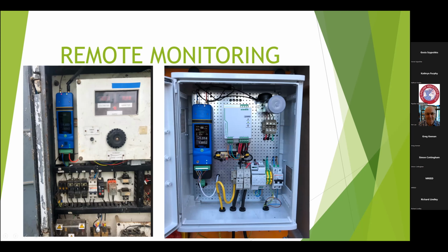There's another example of a very old transformer rectifier here, where this knob is connected to a big rotary transformer. As you turn it round, you increase or decrease the amount of AC, and then it rectifies it. And this remote control unit was installed retrospectively on this. So the output from this is now controlled by this unit here, which you can operate remotely. And this again is the modern equivalent, with the unit displaying the pipe to soil potential and the voltage out from this unit here. And this blob that you can see here is surge protection to protect it from lightning damage.